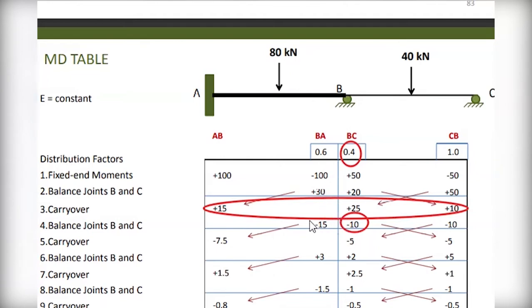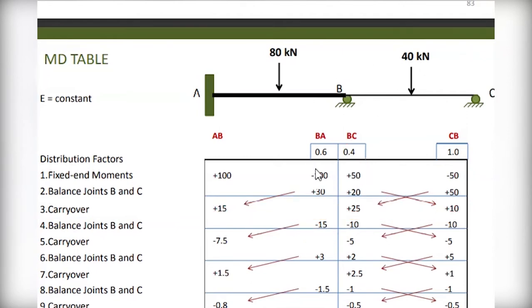So the same applies. In order to balance, because the value here, as we say, is 25, we should have a negative 25. Now this one times 0.4, you create this one, and this one times 0.6, you have this one. It means if you multiply 25 by 0.6, you shall have 15. And this 15 should be negative because this moment should be balanced, as we said before.